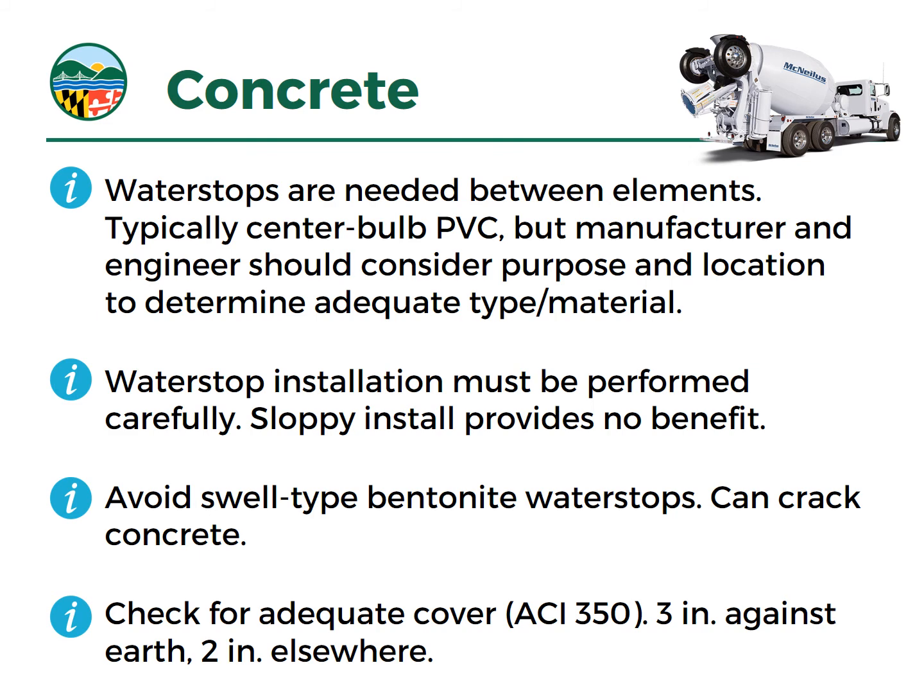Now, before you pour concrete, we want you to check the reinforcing steel to make sure that it's been constructed in accordance with the design drawings, and make sure there's adequate cover too, because water infiltration into that concrete can cause corrosion of the reinforcing steel and then spalling and other types of long-term issues.